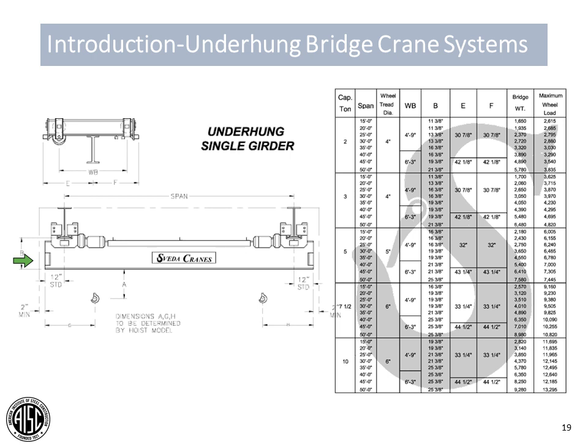One critical piece of information that is not specifically tied to the design of the runway members, but is tied to the overall design of these systems, is this dimension from the bottom of the bridge to the high hook point. Many owners believe or specify a minimum clear height to the bottom of a bridge crane system, and you need to ensure that that does account for this difference in elevation between the bottom of the bridge crane and the high hook height. This is as high as this crane system can pick, and you need to make sure that whatever the owner is going to be hoisting within their facility, this elevation can accommodate that pick.